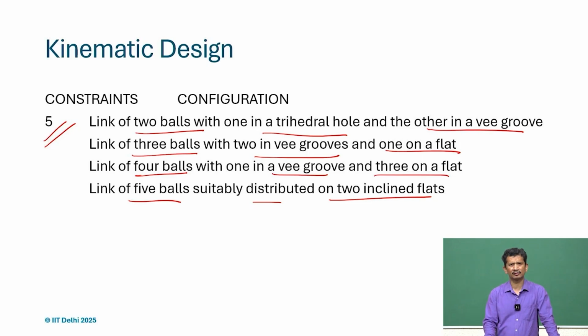So, for instance, what we stated in the beginning and what we usually say most of the time, that for a flat surface you just need 3 contacts. So, you cannot have more than 3 contacts on a flat surface. If there is, there is an over constraint, or there is some elastic deformation in the object we are accounting for.